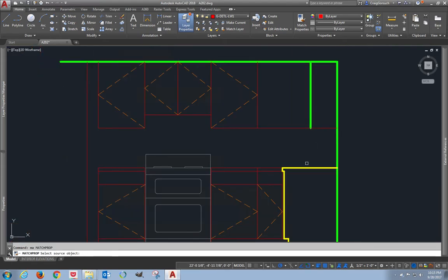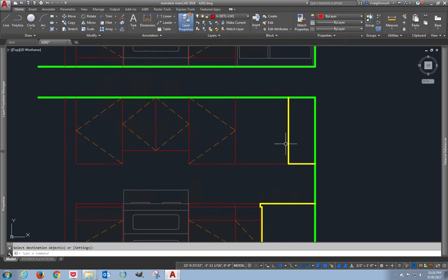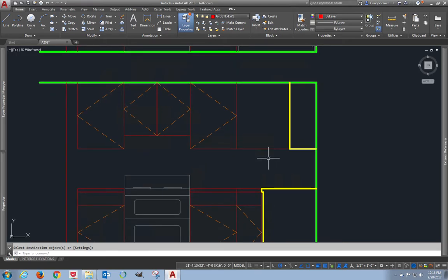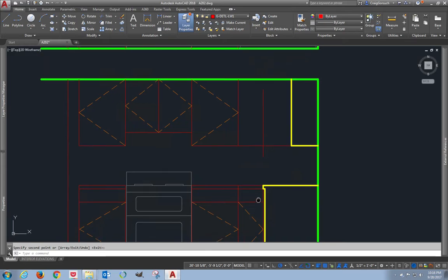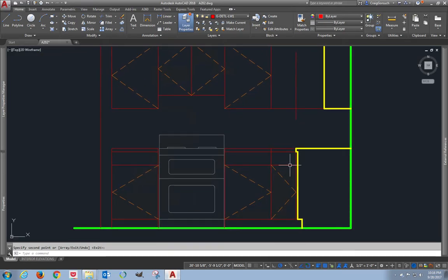Again, this is the most basic way to show a cabinet. There's actually more detail that goes into this. I'm going to leave it like this for now. And this is where things kind of get weird. They don't quite follow the same rules. Now remember one of the things I mentioned a minute ago: cabinets want to be in 3-inch increments along here.